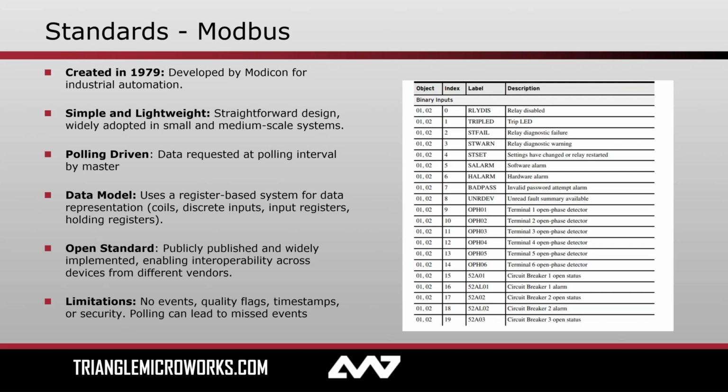Now, the other term that I want to focus on here is polling. So polling just means that I ask for data and I get a response. I, as a client, at some periodic interval, am asking my outstation to report back, hey, what's your information right now? And this is the way that Modbus works. I can request data very quickly, but I only get the value of the data at the specific point that I ask for it.